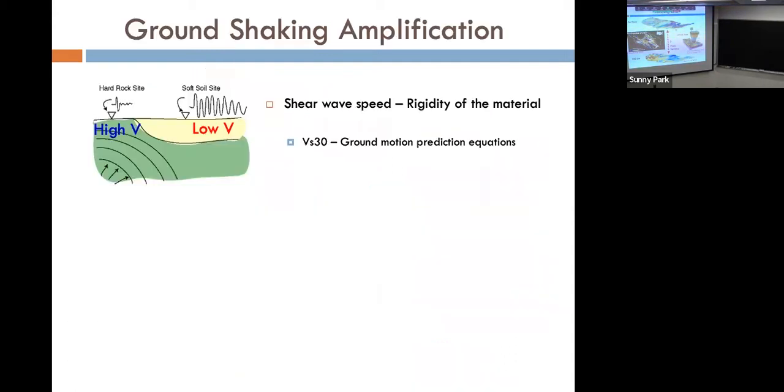Now, another important reason to study the shallow structure is earthquake ground shaking. Here you're seeing a simple cartoon of an earthquake coming in. For the same earthquake, depending on which site you're sitting on, here you have a high velocity hard bedrock site, and here you have a low velocity sedimentary basin site. You can see the records here. Not only is the amplitude big if you're sitting on this site, but there's also this reverberation coming in after. So it's really important to characterize what sort of shallow structure is right under you.